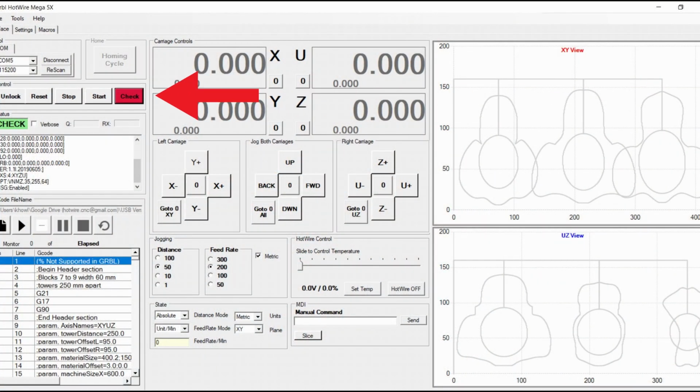We'll also run it through the controller program just to make sure that there's no G-codes that it's not happy with. I had that just over this weekend. A guy had some problems and sent me the G-code, and it turned out to be some spurious code that was getting into the GRBL controller, and it was throwing an error. What it was doing was just pausing.